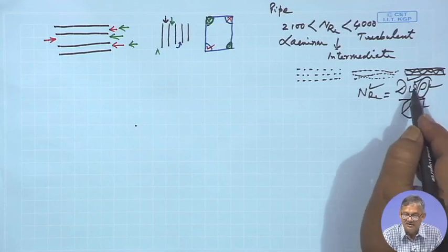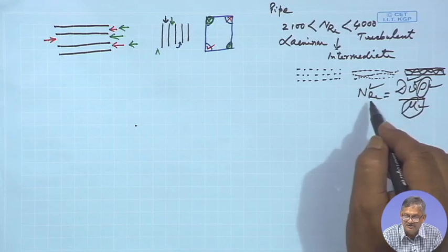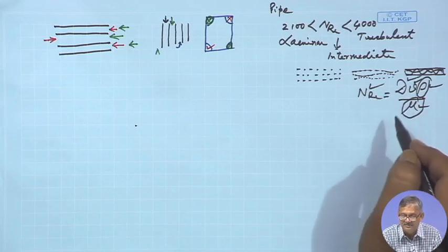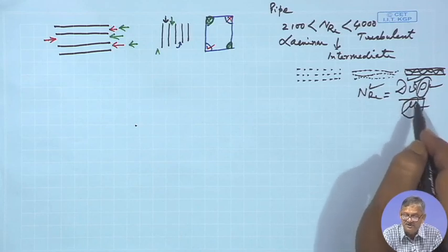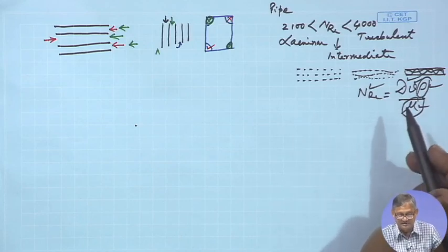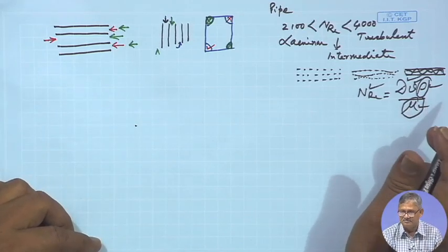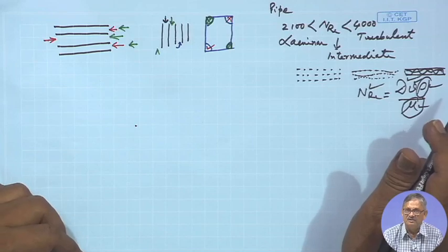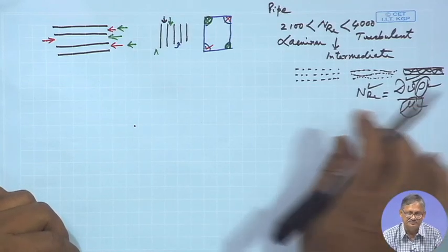If it is high velocity, Reynolds number will be high. If it is low velocity, Reynolds number will be low, for a given d, if the property values are changing, right. That is why I said that knowing the values is very much effective, and in most cases required also, right.